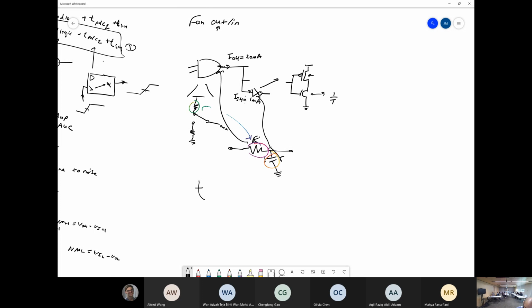Okay, so T doesn't have touch reject? Boo. So your propagation delay is equal to your time constant, right? Which is R times C. But that's not the delay, that's your time constant. So typically your 50% mark is ln2 RC. So that's your propagation delay to like 50%.